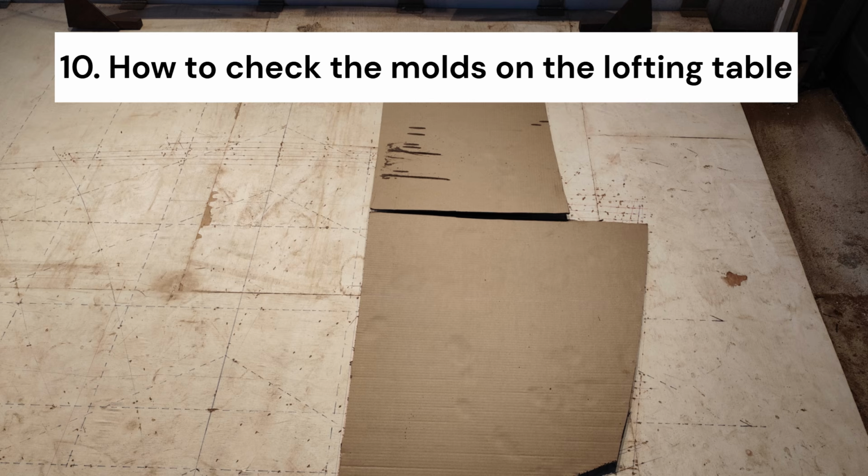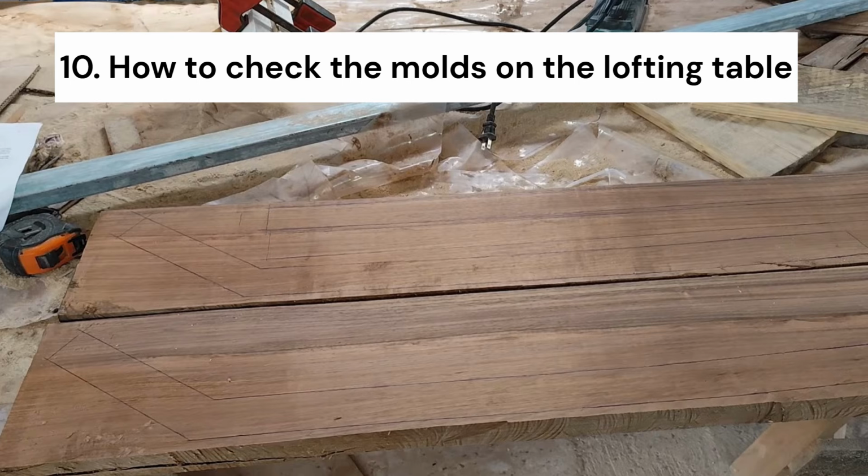If everything is okay with your mold in cardboard or plywood, you can now mark on the wood for cutting. Here are shown markings for one of our stations. Note the reinforcement frames on the upper wood piece. A last thing, station frames like this in the picture, you cut with a bandsaw. Bulkheads you cut with a table saw or a circular saw.